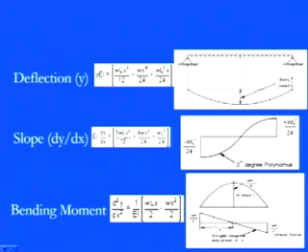In these terms, we have the square into length, which is already cubic, and this is cubic, so we have a third degree polynomial for the curvature path of this slope. Though the slope is very small, it has a third degree polynomial in its curvature. At this particular corner, where x equals 0, we have minus WL³ by 24, and at x equals L we have plus WL³ by 24.